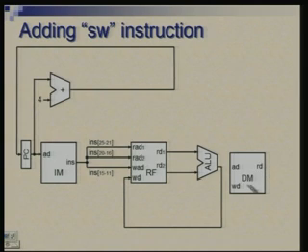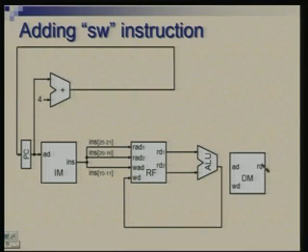In fact, some memory modules have these common. Okay. There is the same set of wires which are connected to memory, through which you can send the data in or take the data out. So, that data terminal is a bidirectional one. Okay. So, there is one address line and a bidirectional data line. In this case, of course, again for simplicity, we have separate read and write lines, but there is a common address line. This is also a single port memory with a single read port, and that is all.